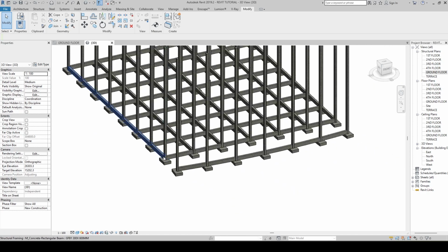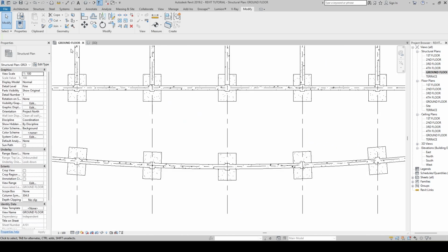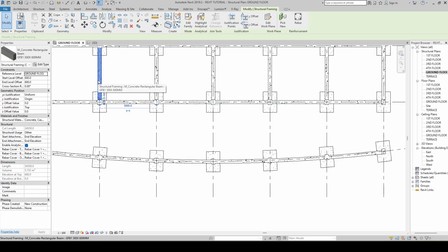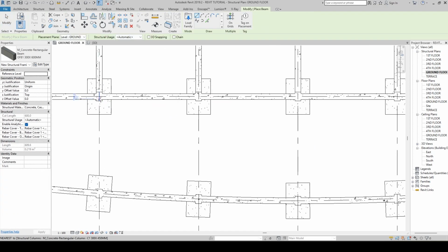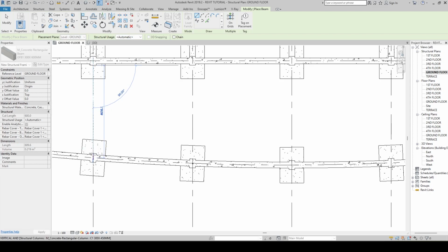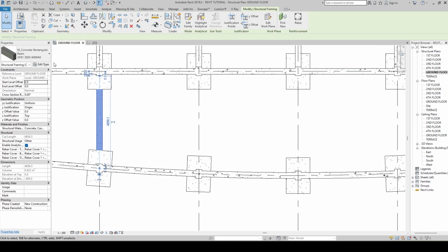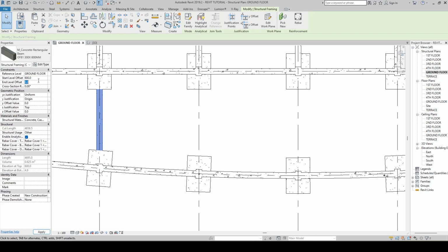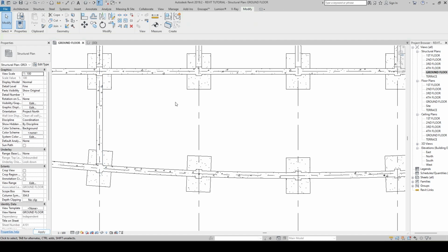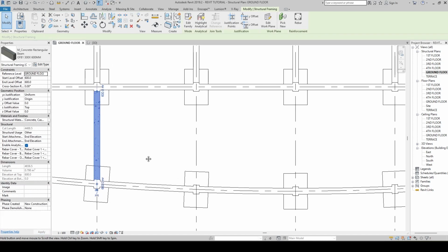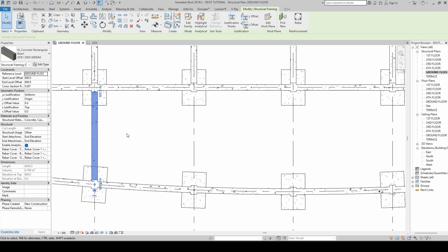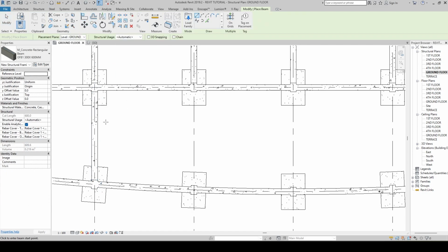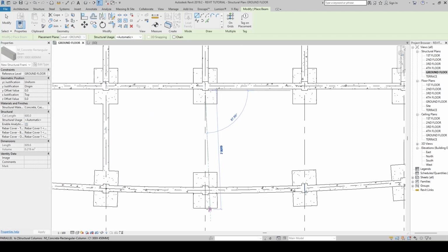Yeah, so now I think I need to connect these beams, that's all. I'll go here, I'll add the beams once again, CS, connect these beams with here. Okay, again I'll take 600 mm as the offset, again 600 mm. Okay, fine. I'll keep the CS, and I add the beams from here to here, again from here to here.